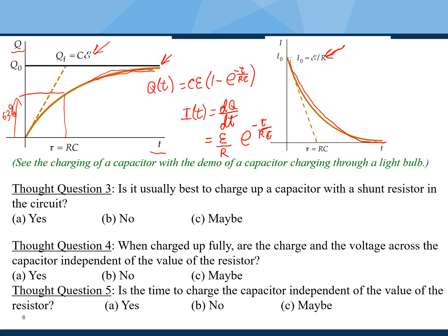The shunt resistor was essentially the resistor R that you saw in the previous circuit, and a capacitor can discharge very rapidly if it is not provided with a shunt resistor. In that situation, the current I can become very large, and therefore it can burn out whichever circuit it is trying to get through.